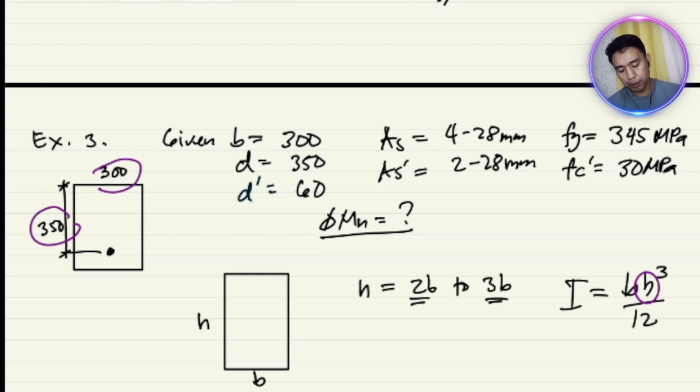Okay? So sabi mo, sir, why not na palaliman natin yung beam? Now, I told you in the first video na may mga constraint. Sometimes yung architect is mag-limit lang ng depth ng beam. Okay? Kasi nga kung lalong lalim ang beam, possible na mauntog ang tao dito. So that's ma-fail ka sa serviceability or sa function ng structure kung lalim na ang beam.